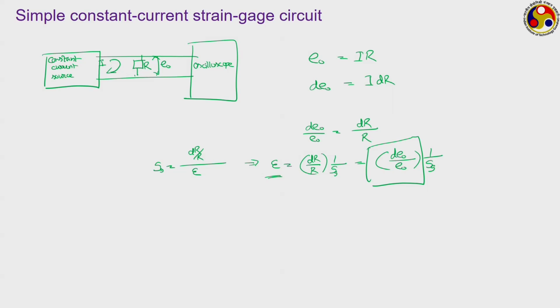Here, just one final thing before I move on to another topic, one final thing I would like to mention about the bridge circuit. We know that commonly in a bridge circuit, we have 4 resistances like this, and in the quarter bridge configuration only one of these resistances is the strain gauge, like this one. Say we generally keep this part open and this part is connected to the strain gauge, which may be mounted somewhere here.